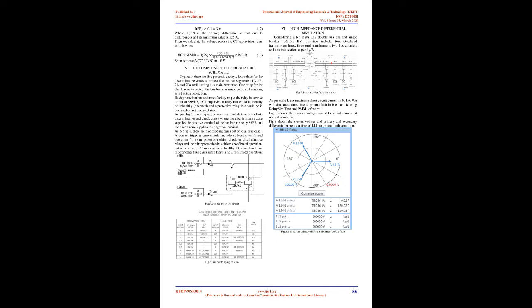Design of nonlinear resistors, Metrosils, R_NLR. During internal faults, heavy current will flow in the high impedance circuit, which will make it subjected to a transient high voltage until the fault clearance. This high voltage can damage the whole circuit insulation. That's why we need voltage-dependent resistors called Metrosils to suppress the high voltage by providing a low resistance path. First we need to check if the maximum RMS voltage during maximum fault current is more than the maximum permissible voltage of the relay system; if yes, we will need Metrosils.